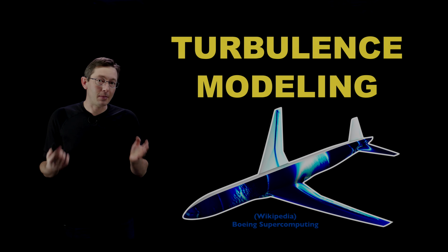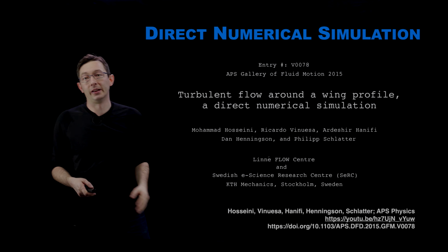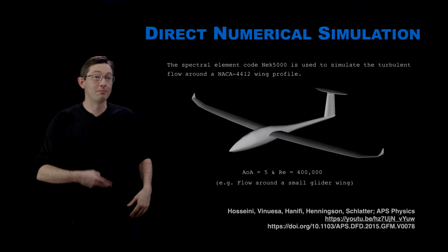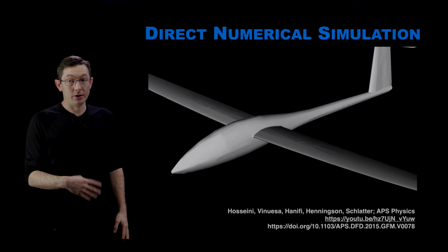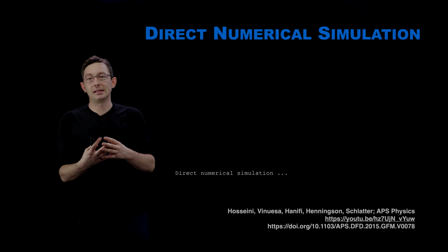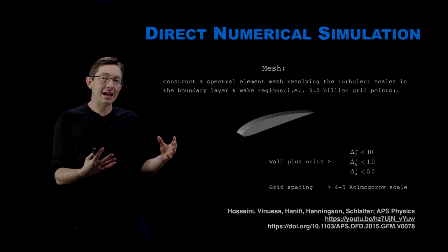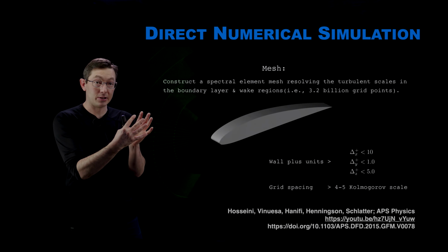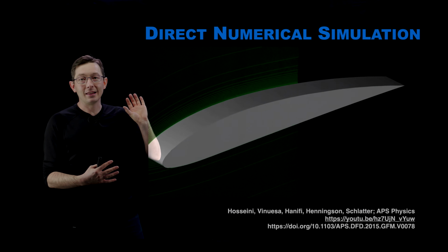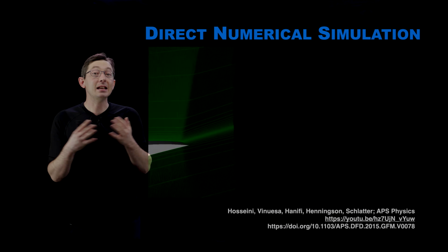Now, we, in general, might want to solve the full Navier Stokes equations with a direct numerical simulation, which would resolve all of the scales in space and time. So here I'm going to show you one of my favorite movies of a direct numerical simulation. But it is typically very difficult to simulate these fluid flow equations over the entire aircraft or over an entire automobile. So instead, what researchers often do is zoom into a particular piece, like this section of an airfoil, and solving the full flow field equations for this section of the airfoil is still exceedingly expensive.